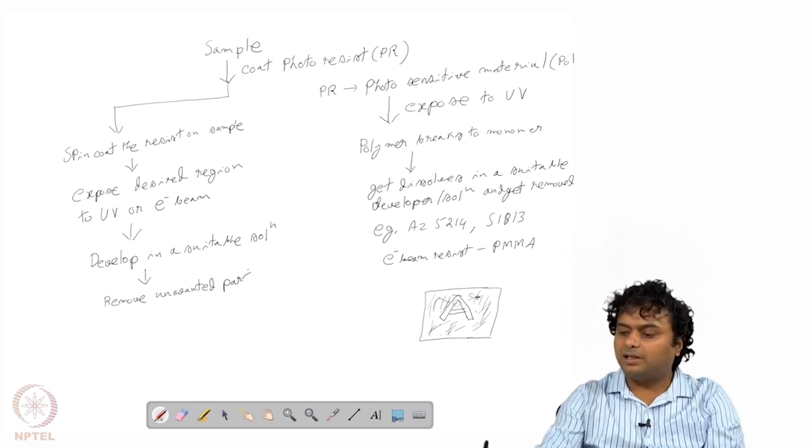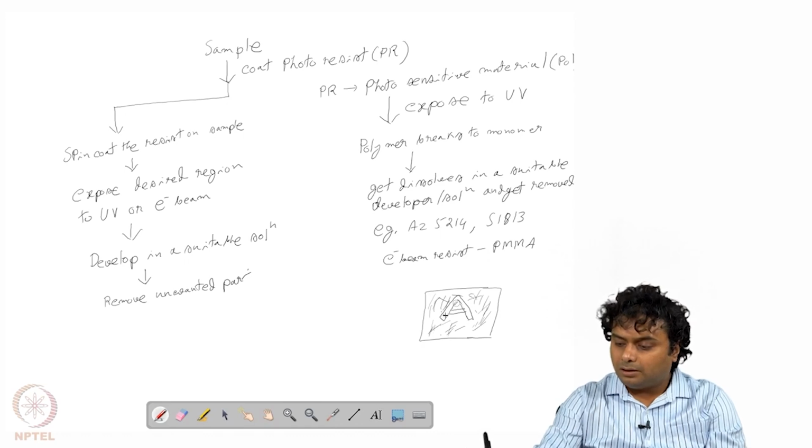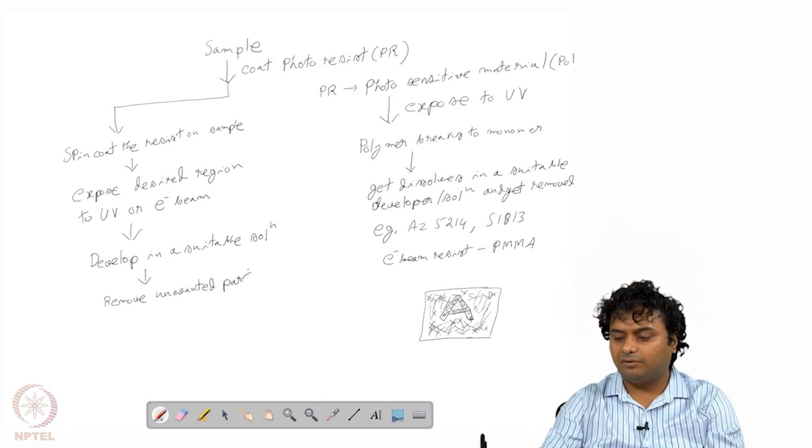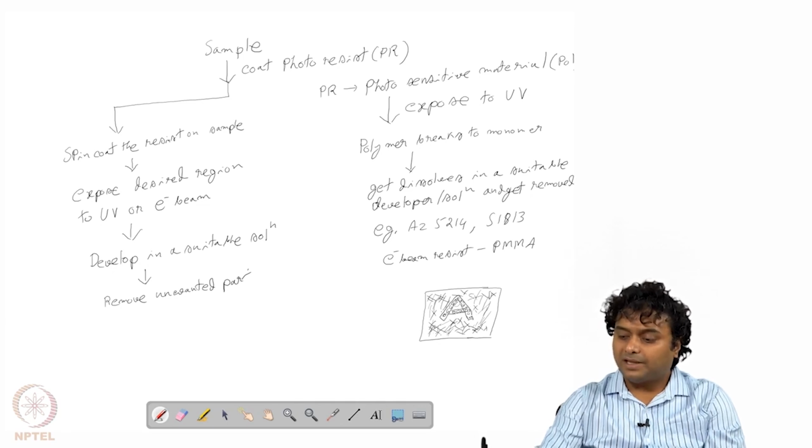So if this is a silicon wafer, then only these regions, the silicon is exposed, because PMMA has been removed from these circle regions, right. Whereas in the other parts, like these shaded parts, there PMMA is still there, correct. So this is like we have written this A pattern in a very fine scale, like in micrometer or nanometer scale on a silicon wafer, such that the A space is silicon and the other space is all polymer.